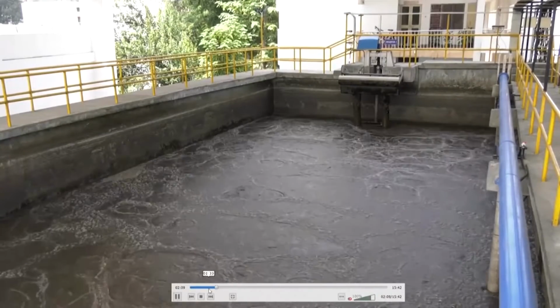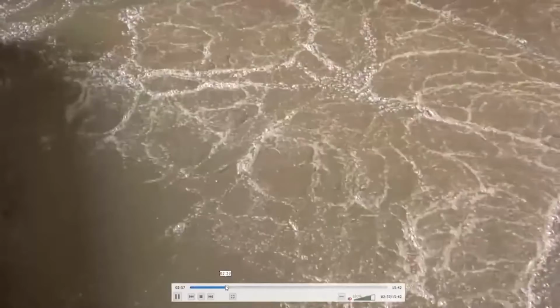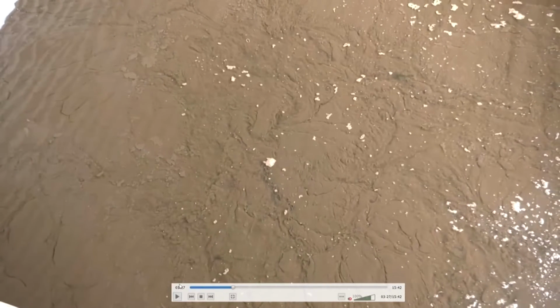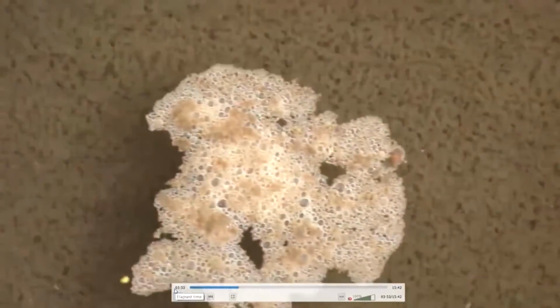You can see that out here, right. During this process the microbes are degrading the relevant sewage, and after I stop aeration, let us say, you see the flocks. These are different kinds of... okay, now you can see the flocks more clearly, right. Let me see if I can get a better shot somewhere out here, okay. And these being heavier will also settle down. So, I guess you can see them already starting to settle down.